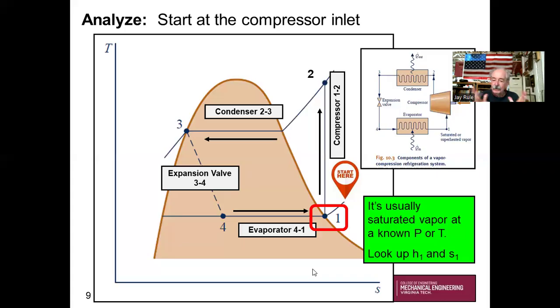Well, what are you going to do? You're going to look up H1 and S1 immediately. If you know P1 or T1, it's a simple matter to go to your property tables, look up H1 and S1, and write those down.